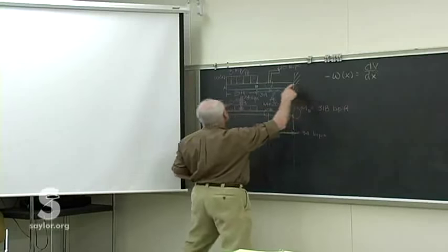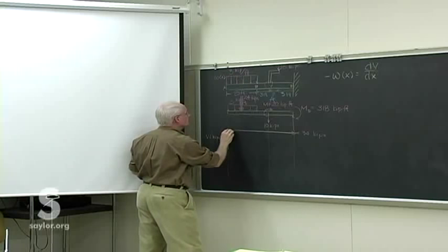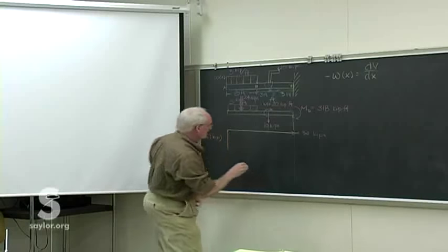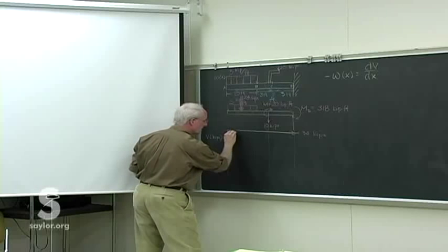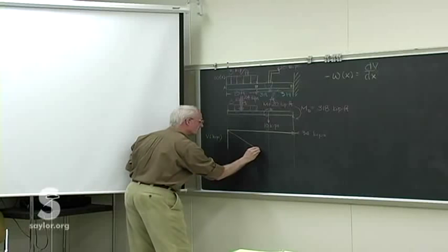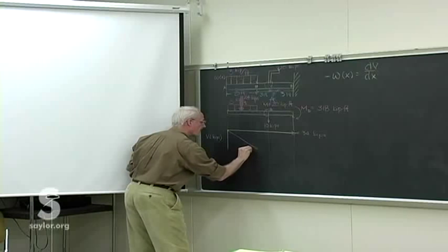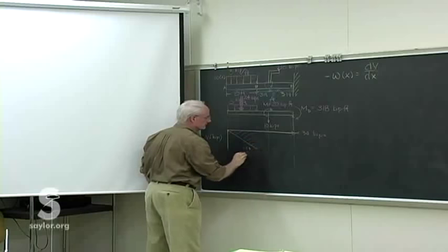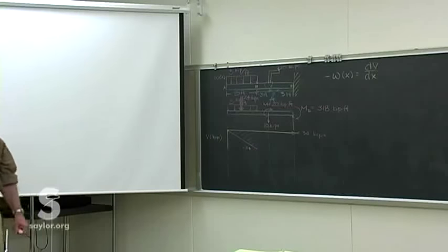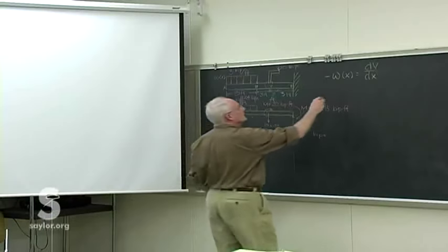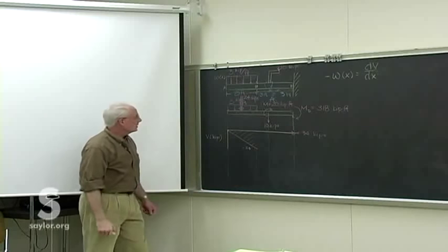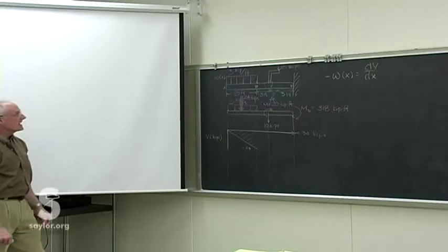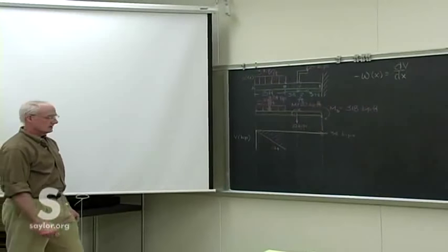So we have a negative slope of 3 kips per foot. And that would go for 8 feet, so it would take us down to about 24. So I can leave enough room. Is something like that. And we can do that remembering this relationship between the shear and the distributed load without having to actually make the imaginary cuts and figuring out the internal loads there.